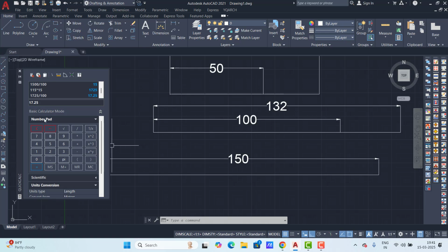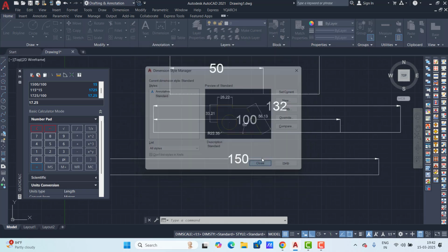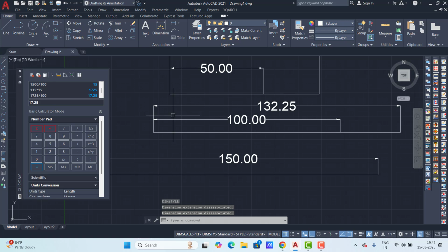I want to delete the overlapping objects and keep only a single object. With the delete duplicate objects option, we can finish overlapping objects in one time. So go to Modify and select this option. Otherwise, you can use the shortcut OVERKILL. Type OVER, press enter, and select all objects which have overlap.